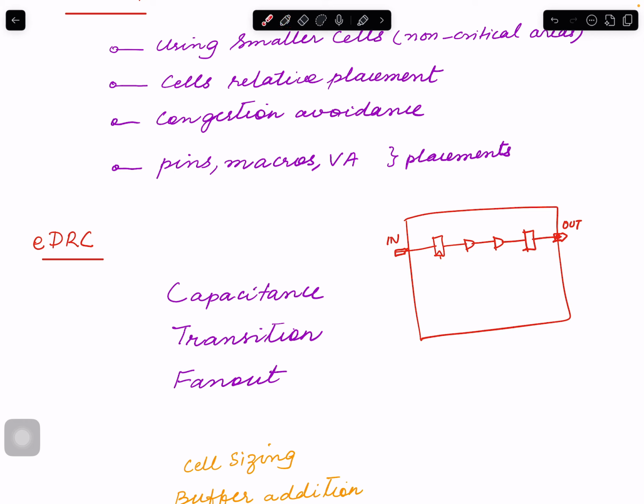You apply a transition time, that is the constraint you give at the port. I'm not talking about that one. You're applying a stimulus, saying on this port of my block, you know where it's coming from, it will have 100 picoseconds. So you apply 100 picoseconds here, and you put an output.